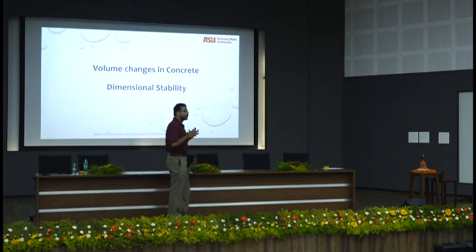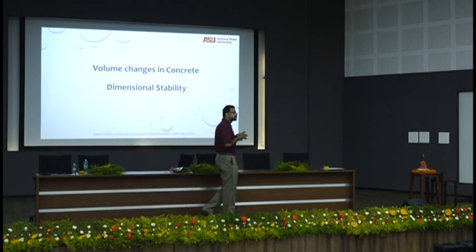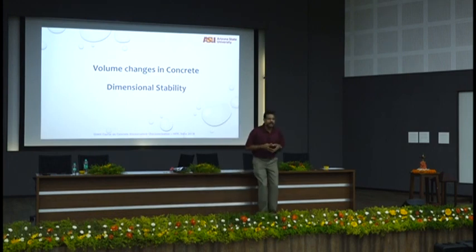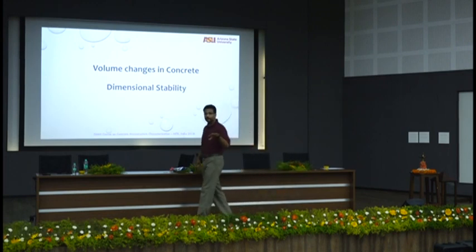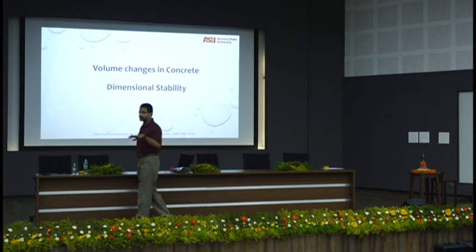Now, think about what happens when volume changes happen in a material that is already in place. In the very fresh stage, when things are moving around, a change in volume can be easily adjusted internally, right? Because things are very fluid, change in volume is not going to be a problem. But also remember that every concrete structure that you ever build has some level of restraint.